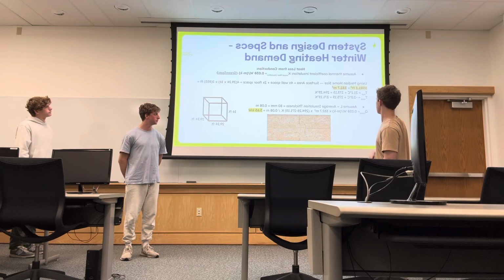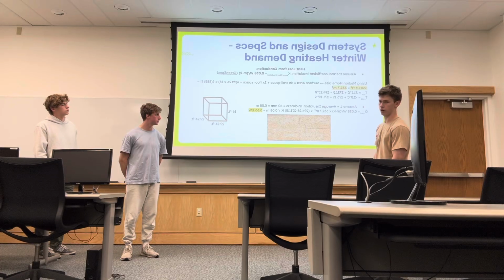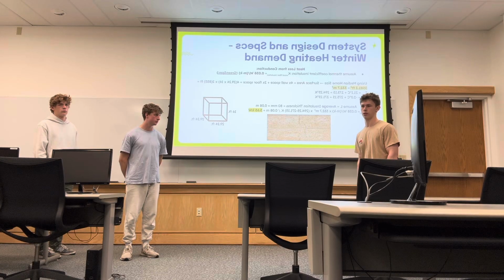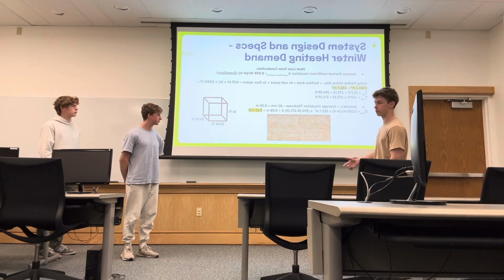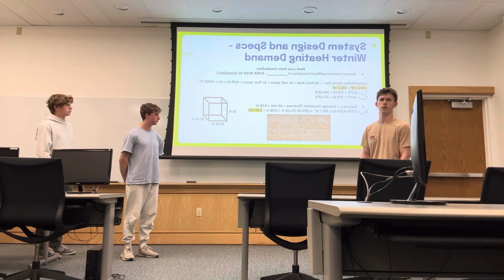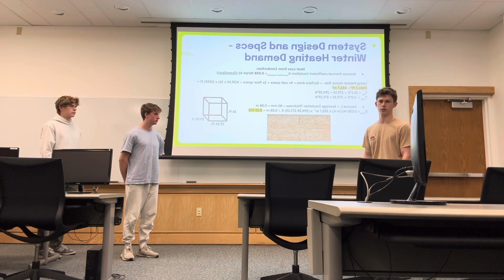We have 332.7 square meters of area for this heat to be lost to, with an inside temperature of 21.1 degrees Celsius and an assumed outside temperature of -2 degrees Celsius, which is the average temperature in Pennsylvania during January, when we're really going to need this heating system working well.